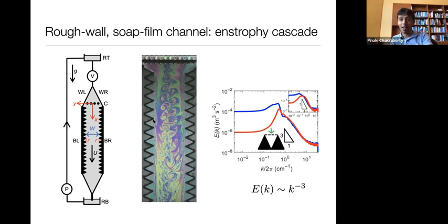Further, if I want to do these measurements carefully, the Reynolds stress over here is going to be different than over here, and different than over here, and so forth. In other words, I'm going to have a streamwise profile of the Reynolds stress that has some shape that looks like this, and then take an average of the whole thing. In other words, I can't just have single point measurements with an LDV, or if I want to do that, I would really have to put a very finely spaced grid.